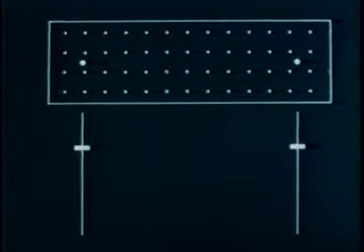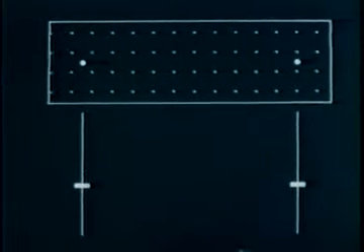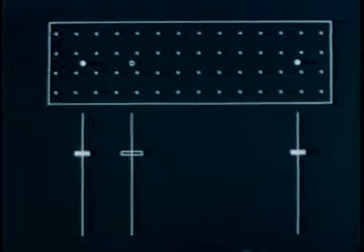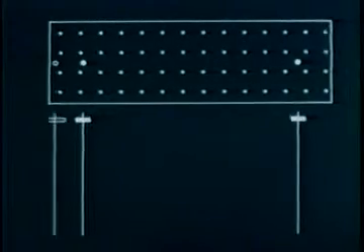Since in this case we distributed the tracer uniformly, the radioactivity at the two laboratory points is the same, but is changing with time. We can add radiation counters at the laboratory points. The solid bars on these Eulerian radiation counters indicate the level of radioactivity at these two laboratory points. We can monitor the level experienced by a material point traveling from one laboratory point to the other by watching the open bar on the Lagrangian counter carried by it.